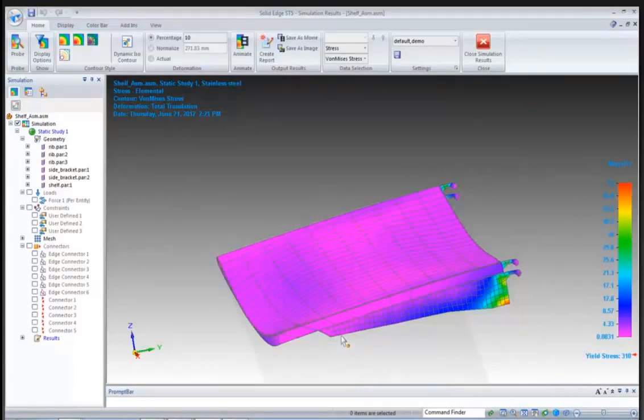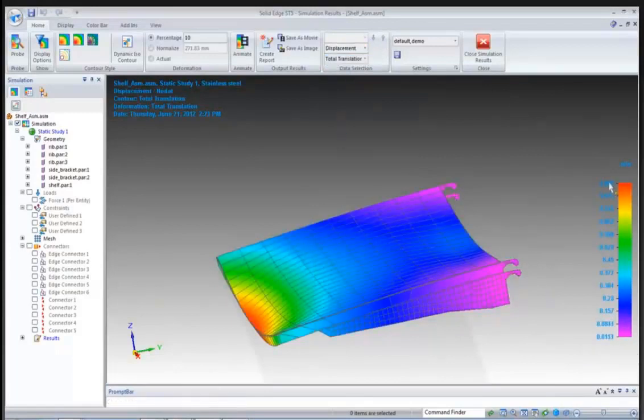Now, my other concern is my mesh, because I'm using a mesh instead of the actual geometry, and I've got these little squares trying to simulate or model curved surfaces. So the smaller mesh I have, the more accurate my mesh is. But that drives up my solve time. So what I need to do is figure out where it's valid. Where is that trade-off? So that's what I'm going to do. Let's take a look at displacement here. We got under a millimeter, so we've got 0.888 millimeters.